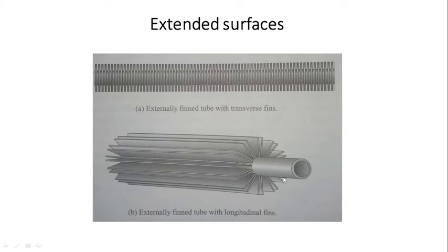The integrally formed tube can be used to create the fins on the inner as well as the outer side of the tube. Another technique is non-integrally formed fins, which is obtained by attaching metal pieces on the outer surface of the tube.